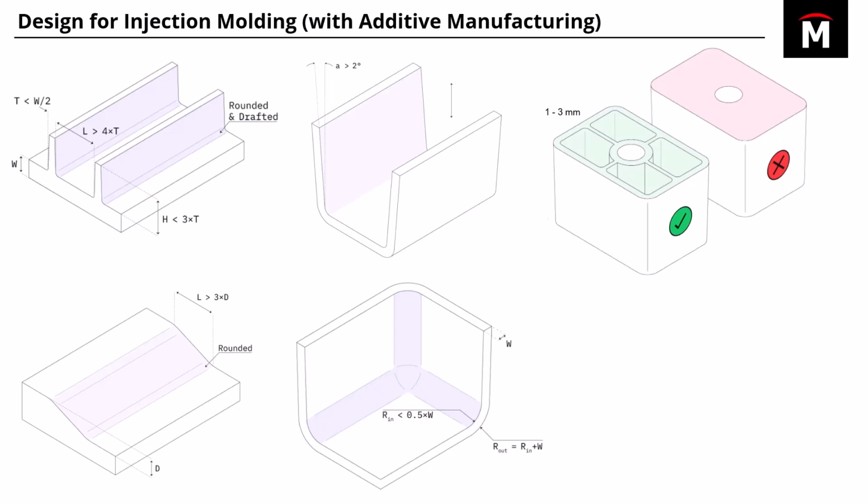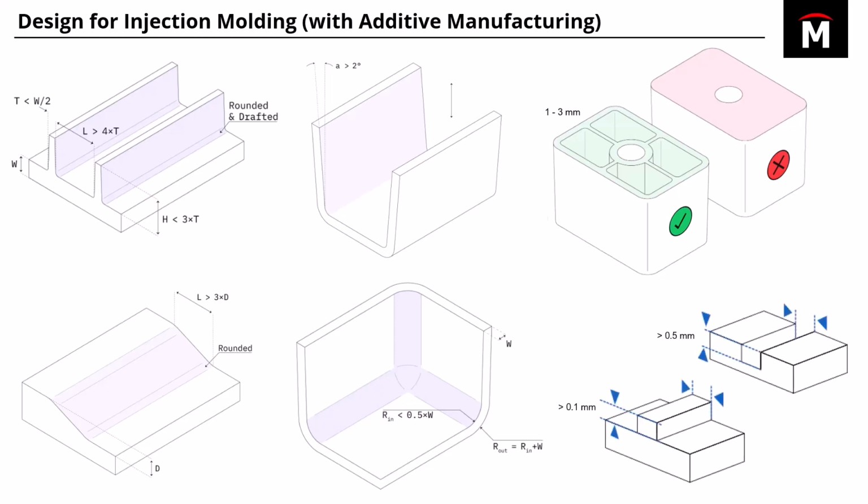This kind of goes back to what I mentioned earlier about consistent wall thicknesses. So kind of in that upper right, you can see you want to avoid having just a solid block of material. It's more advisable to have that block shelled out, and aim for wall thicknesses of like 1 to 3 millimeters. And lastly, just 2 things to consider there with engraves and with emboss features.